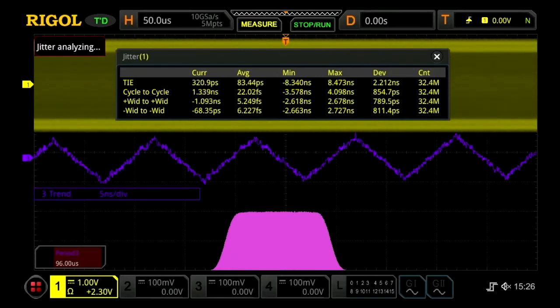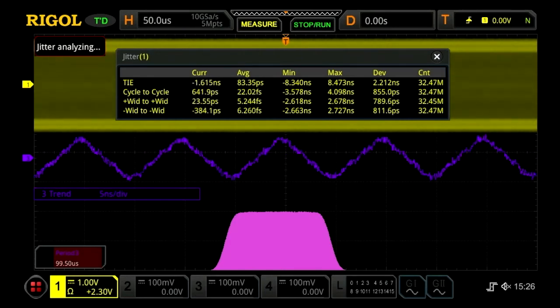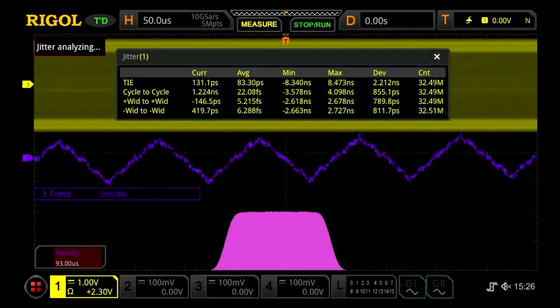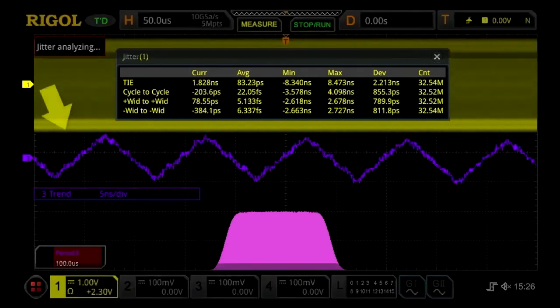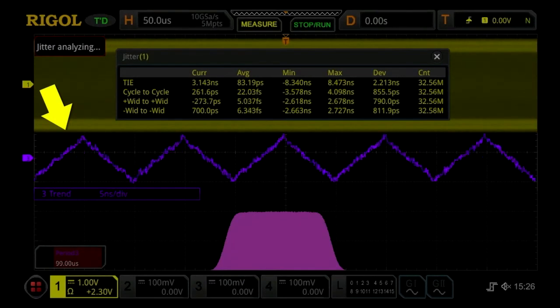Jitter analysis is the characterization of the clock timing. Here we are looking at 35,000 clock transitions on channel 1 from a serial data transmission. TIE, or the time interval error, is one of the most useful methods for visualizing subtle changes in the clock frequency. The purple math trace is the TIE trend. This shows the sum of the errors in the period from the expected clock.